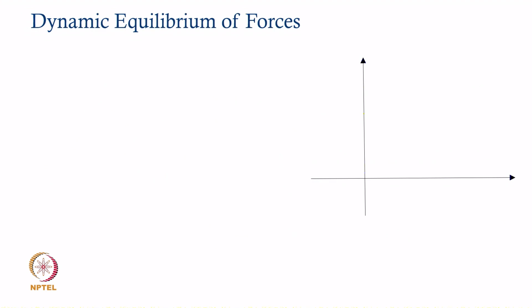Okay. Now, the equation of motion that we have all the time talked about, m x double dot plus c x dot plus k x equal to f of t, we shall have a vectorial representation of this equation. Please make a note that this equation is a force equilibrium equation. So, all of these terms that you see in this governing equation of motion are nothing but forces. This is an external force, an externally applied excitation force to the vibratory system.